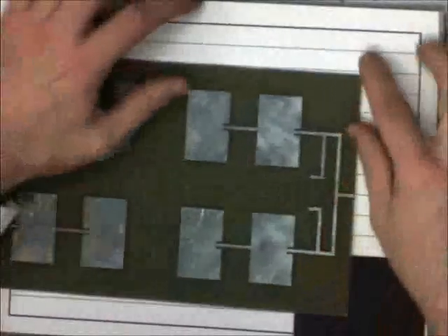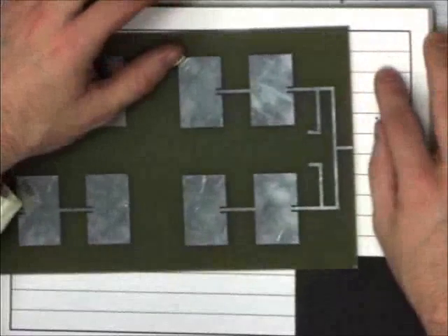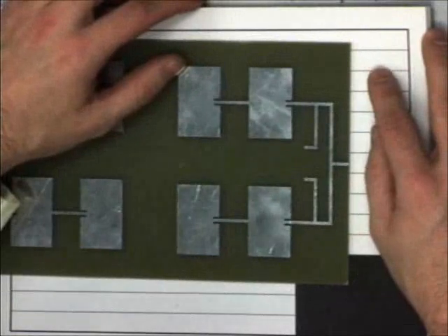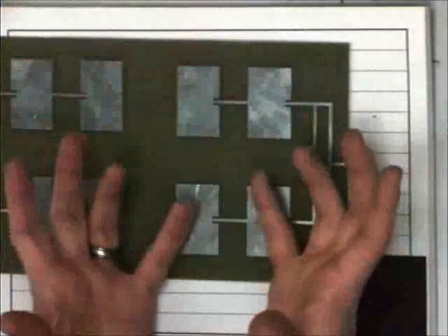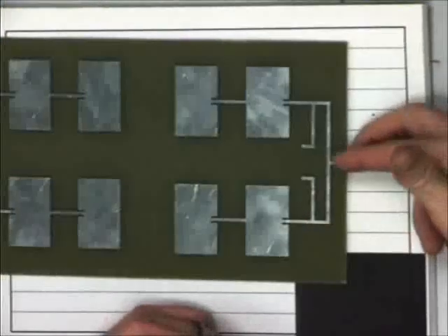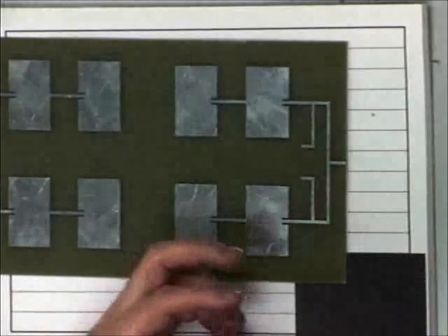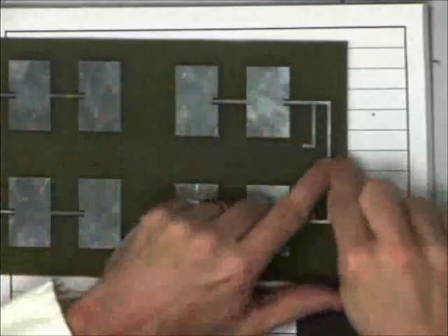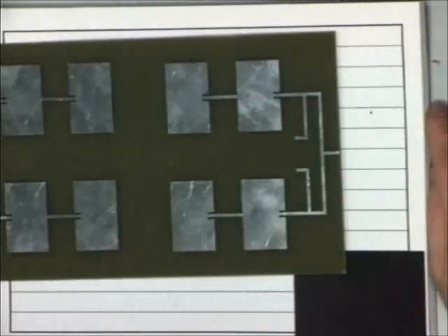So, yeah, Lam, you have a question? You send signal out. That's right. They both transmit and receive. There's something really interesting in electromagnetics called the reciprocity theorem, which says that you can put a voltage waveform here and they radiate with a certain pattern. Or you could put a voltmeter at the end of the line and signals will experience that same absorption pattern as they come in and excite a voltage at the terminal of the antenna. So an antenna can always be used as a transmitter and a receiver.